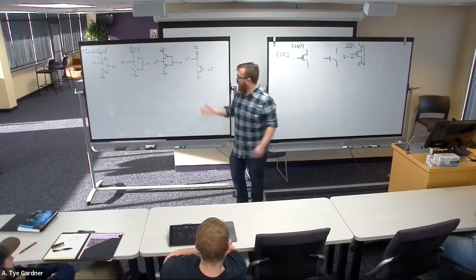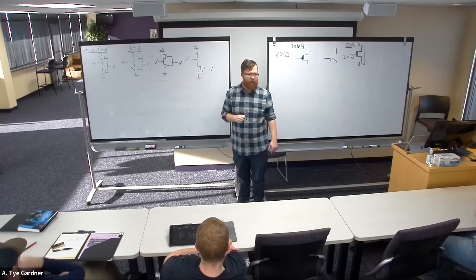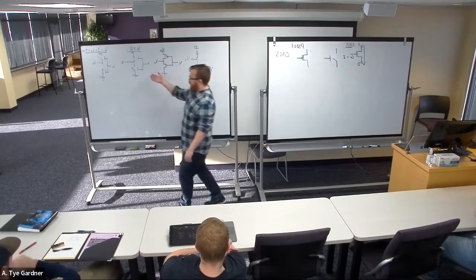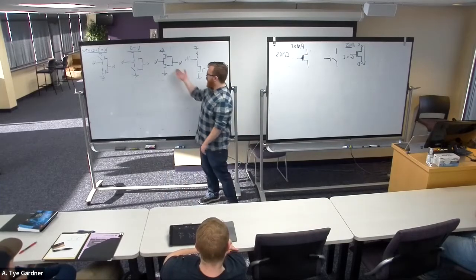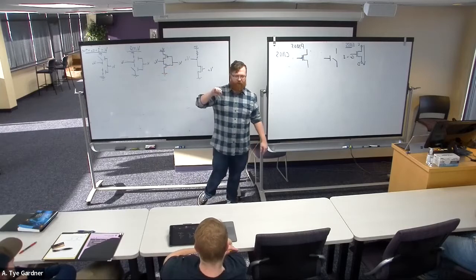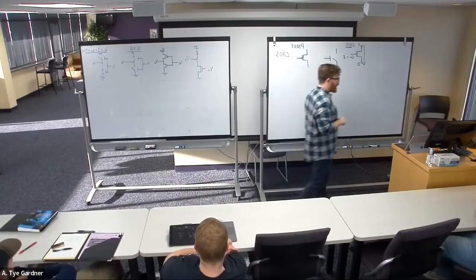It doesn't burn power if I'm open, but it's burning power half of the time if you assume equal distribution, right? So not only does this save us area, it also saves us power other than whatever is consumed by a small amount of leakage current, which is really nice because we don't want our cell phone batteries to die faster than they need to.